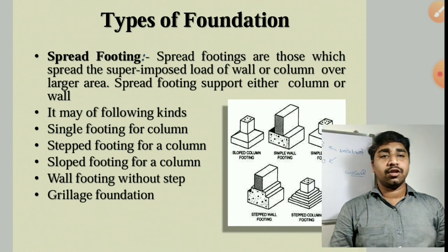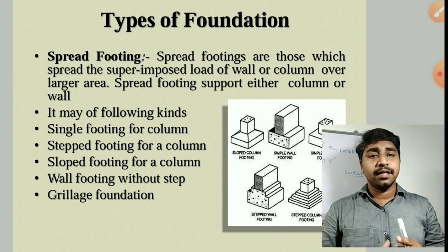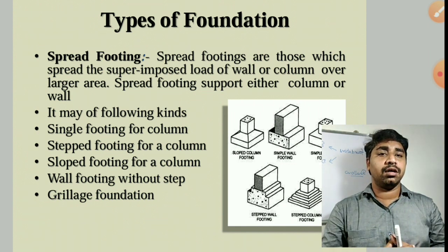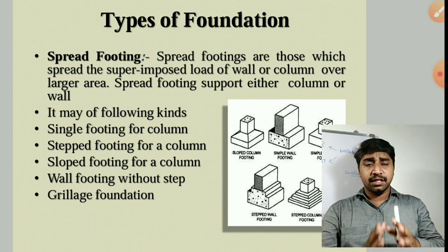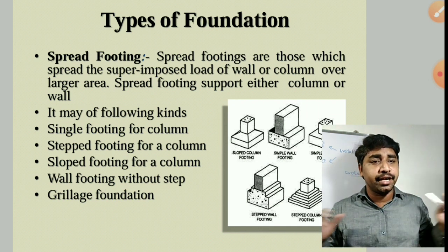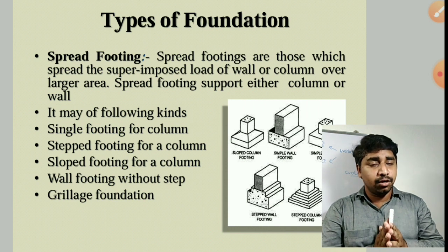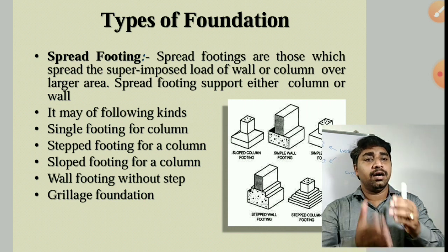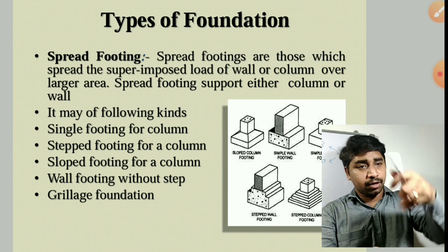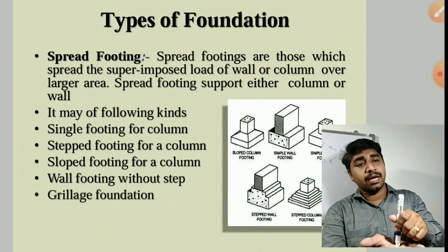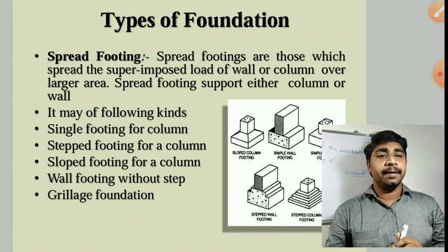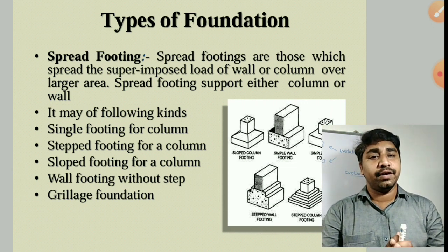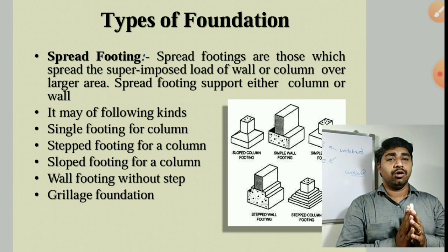The spread footings are those which spread the superimposed load of the wall or the column over a large area, where the load coming from either the wall or the column onto the foundation below is going to be distributed uniformly. Then it is called a spread footing. It is going to spread the load.